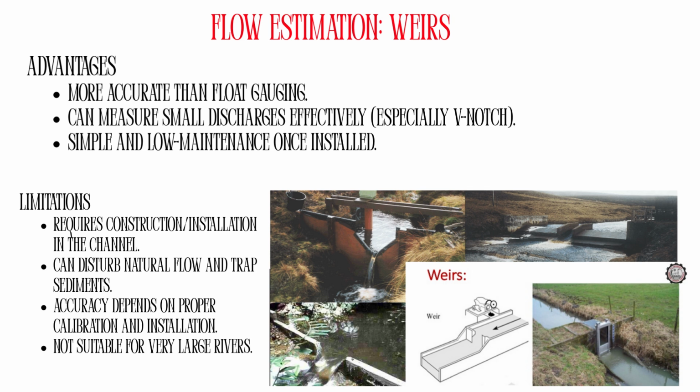Limitations for this method. First, requires construction, installation in the channel. Next, it also can disturb natural flow and trap sediments. Third, accuracy depends on proper calibration and installation. Last, this method is not suitable for very large rivers.